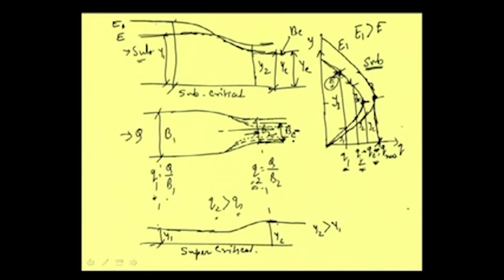So, that is actually one of the very important phenomena which creates problems in our engineering activity, because as we were discussing many a time, we are required to narrow down the width of the channel. But if we reduce the width up to a certain point, we can get critical depth. If we reduce beyond that level, the depth or flow condition there will remain critical, but the upstream side will be rising, that is, it will impound water on the upstream side, and that creates problems.